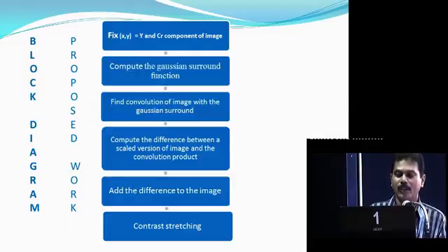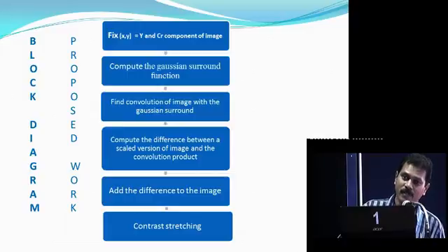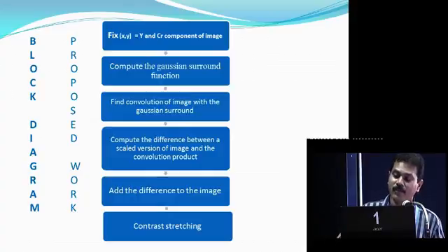So in order to restrict that, some have proposed the RGB to HSV model, where only the value is taken. And in our method, since the underwater scenario is considered, and underwater always attenuates red color, instead of using HSV or RGB directly, we have taken the YCbCr model, and Cr, since it's attenuating more. The YCbCr model is taken, leaving the Cb part, then it is the same method, thereby obtaining better results.